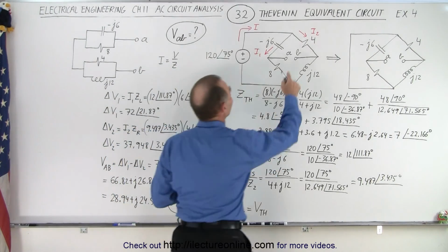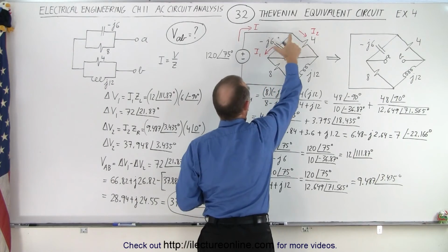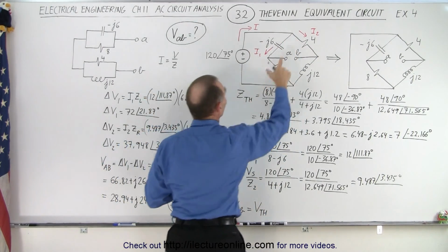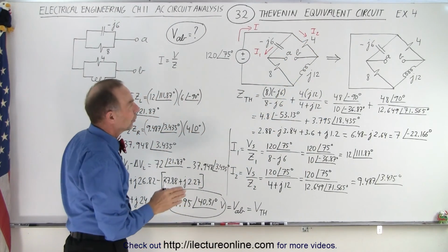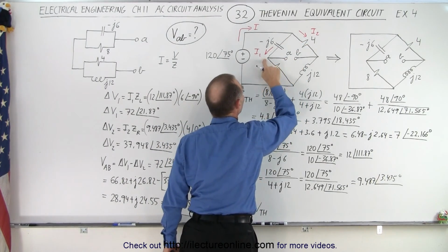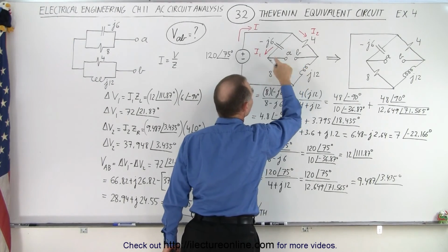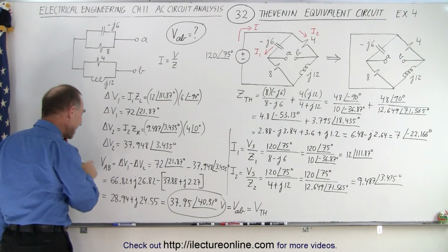They started at the same point, same voltage point. The voltage drop here, the delta V1, was bigger than delta V2. So since the voltage drop was bigger here than it was there, then this will be at a lower voltage and this will be at a higher voltage. So when we go VAB, that's lower voltage, that's higher voltage, I really need to take the negative of that.